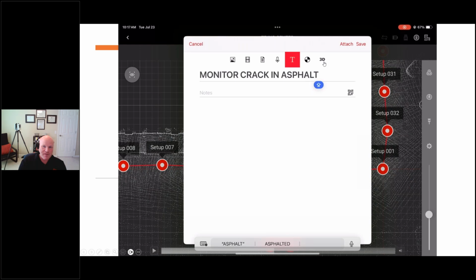And if you have an iPad Pro or an iPhone Pro, you can actually do things like, if it's a lift station or something, the RTC has a half-meter scan too-close cutoff, and most scanners have that distance standoff they need to generate a reliable point cloud. But with the IR scanner, obviously no statement of accuracy is made, but if you just want contextual information, like under a desk, in an interstitial space, a pump station, a tight closet, you can paint additional data and then bring that cloud in and link it to an actual scan.